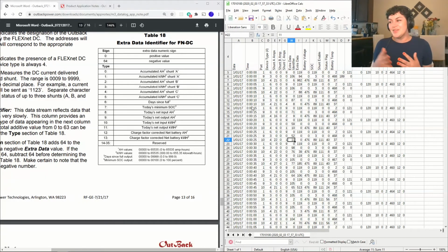This data logging will show you that. Sometimes an inverter shuts down early, and you can see you hit your low battery cutoff. Either your cutoff is too low, or your batteries aren't big enough and you're getting to that point really fast. The inverter's operating as it should.